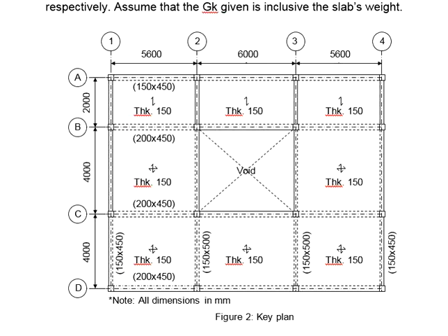You need to know that the slab is monolithically cast together with the beam. This is to ensure that the stress can effectively distribute from the slab to the beam. If you observe the reinforcement in the beam and the slab, taking this end as an example, this is the beam and this is the slab.